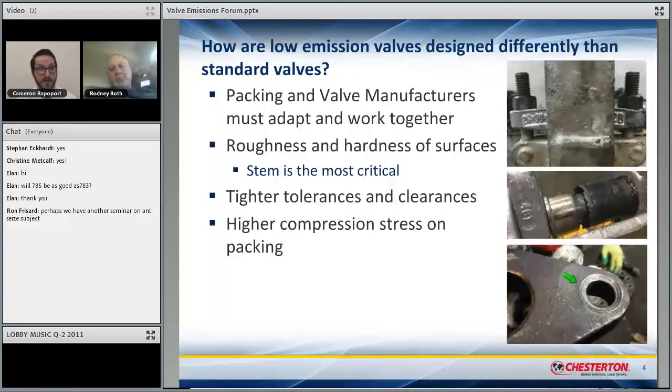Yeah. So I'll point out that a reason why we run into these issues specifically is one of the things we do here, and one of the things that Rodney really helps us to run: when a valve manufacturer wants to get certified low E valves, they want to pass a 1624 or an ISO 15848-1. We do that testing and we work together with them to get there.